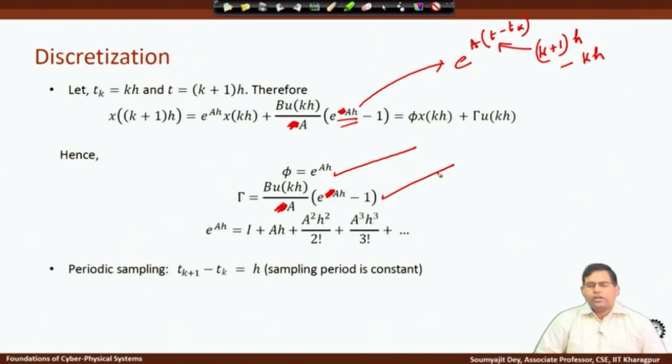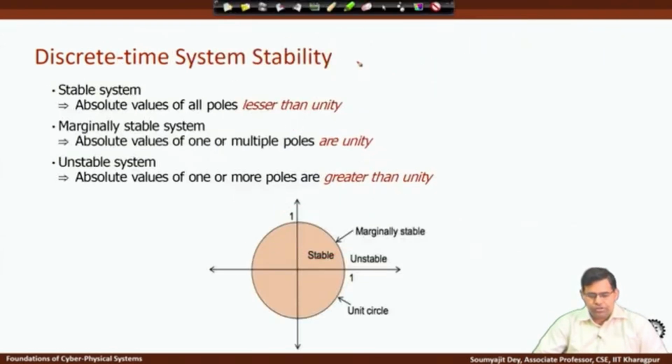So, these are kind of standard derivations from the continuous to the discrete time. You can find them in most of the popular books. For example, one reference is the book on digital controller implementations by Astrom, and you can find this done in a similar method in that book. Like we said, for a given system, if we want to carry forward this discretization, you can even approximate this e series with the first few terms, evaluate what phi and gamma are, and carry on from there.